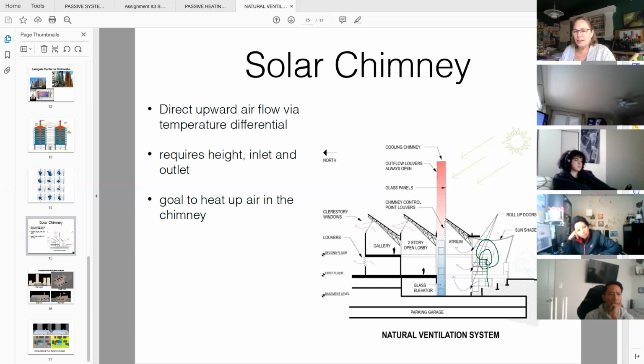People still try to do it. The technology does keep getting better, but at the end of the day, especially if you're up against a budget, keep it simple. Just a window that opens and closes manually to let your air in at the bottom. And in this case, the 100% of the time open top of the chimney, that part of the system works great. The window part, not so hot.